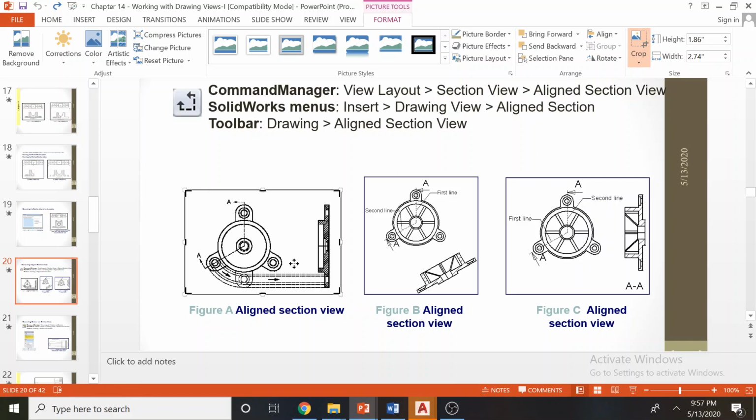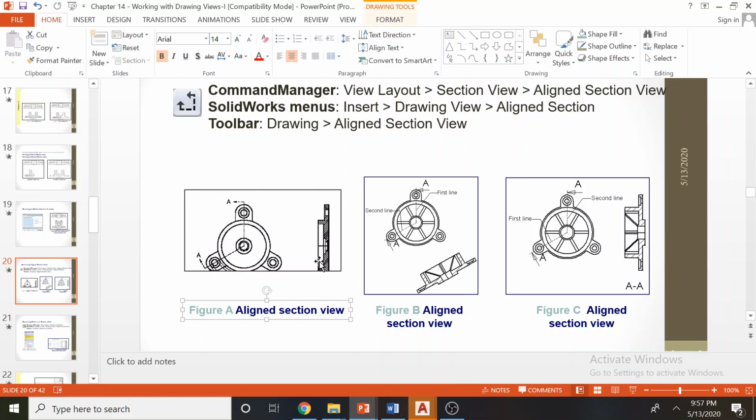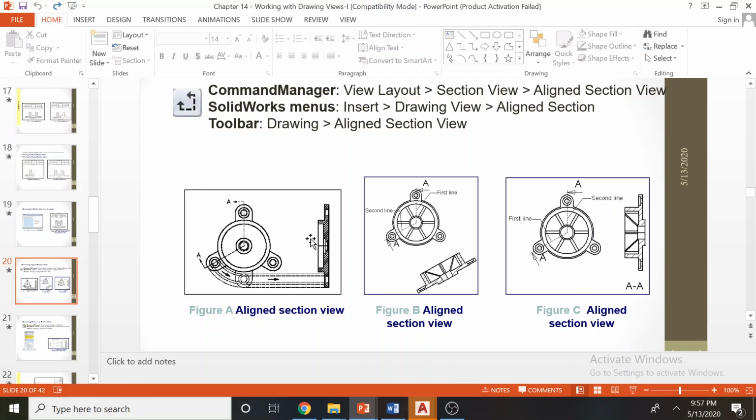Otherwise, if you just cut vertically, this is the drawing we produce. So we cannot give a lot of information at once. We cannot concentrate a lot of dimensions into one area, so it's not going to be readable. That's why we have this kind of symmetric drawing, to distribute our dimensions nicely and present. But the reader should understand there's no part here. It's just a visual representation only.